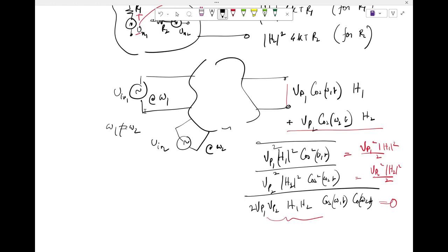Now, similarly, when you are doing noise, noise has all frequency components. And the strength of the noise at any particular frequency is 0, because power spectral density is power within one delta f bandwidth while delta f tends to 0. If delta f is actually 0, which is at a particular frequency, then the noise component at that particular frequency is always 0. Right? So essentially, when you have multiple noise sources in play, it is equivalent to saying there are multiple noise sources at different frequencies at play. Right?